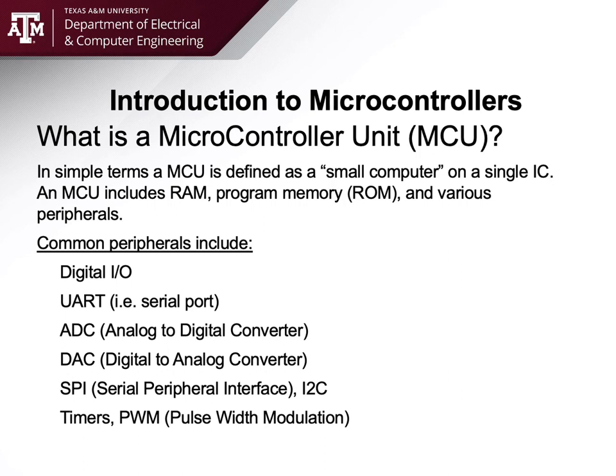It seems simple to say, but if you want to know how many pulses per second you're getting off of a motor, say an encoder on a motor, to know how many revolutions per minute the shaft is actually turning for some sort of control, like speed or position, you would use a timer counter input. You'd precisely time events and also count events. In this case, count pulses over a period of time. Say, how many pulses did I get over 1 second, or over 100 milliseconds, or something along those lines.